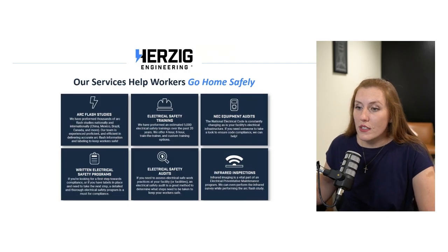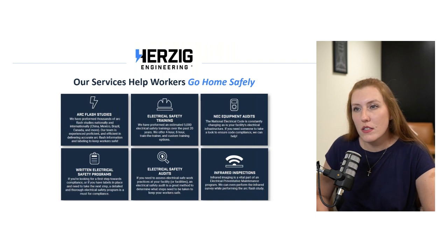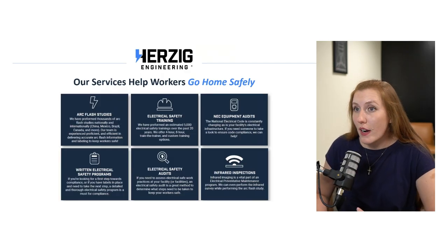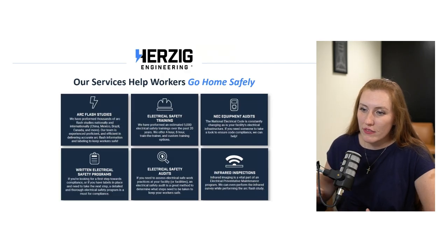Through the process of establishing an electrically safe work condition, you have to verify absence of voltage with your meter, which means potential exposure to those electrical hazards. So PPE is required, boundaries are required, the whole nine yards. Even just to perform LOTO on electrical equipment, if you're exposing yourself to those conductors or circuit parts, you're going to need that study in order to keep everyone safe.